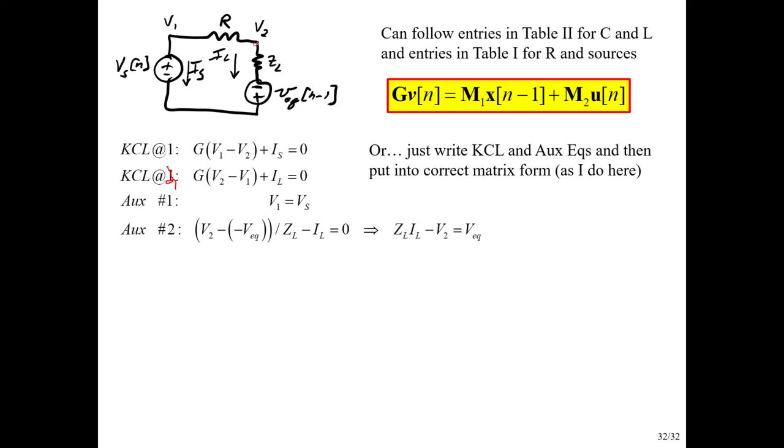So now let's run over at KCL at 2, and we've got V2 minus V1 gives us the current that way. V2 minus V1. And notice that structure. That shows up a lot where you're going one node, you're doing KCL, now you're doing KCL over here. The resistor will show up with those two reversed. So in your circuits book, when you studied this, you might have learned that little trick. So that gives me this going in this direction.